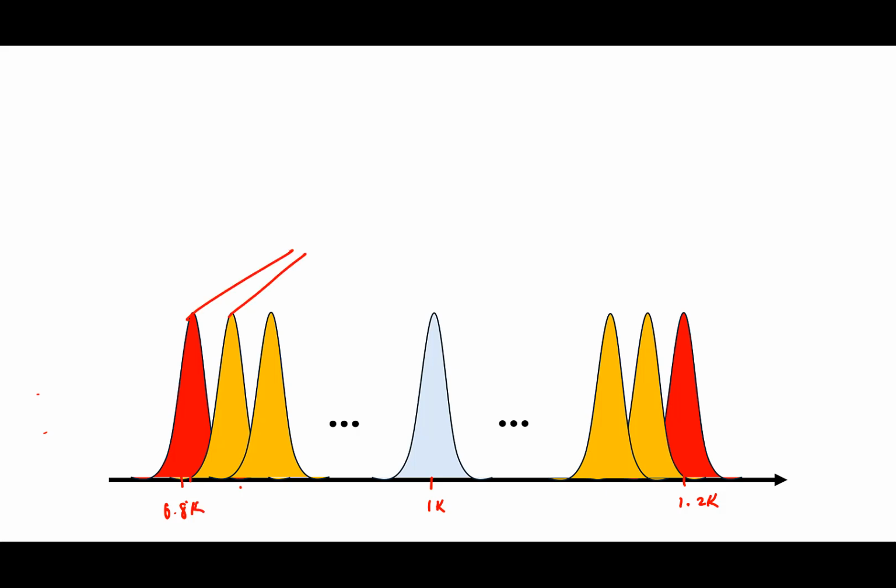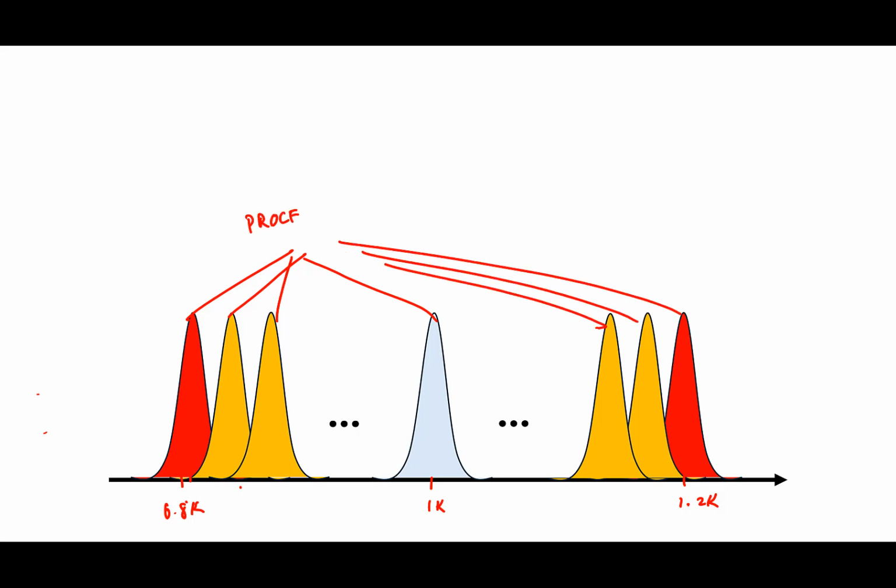And this variation in this mean value, we call it process mismatch or process variation. So this is essentially the chip to chip variation. Now in addition, if you take one particular chip, around the mean you will have variation in the resistance value, and that is what we call random mismatch. This is the terminology that we use.